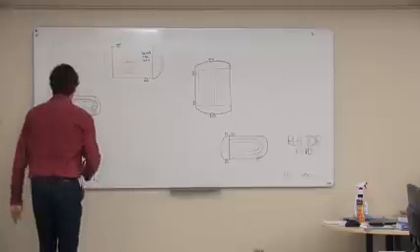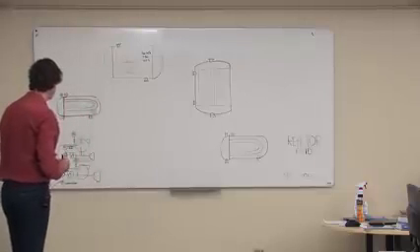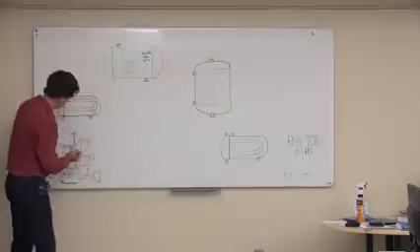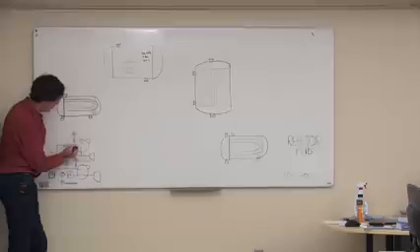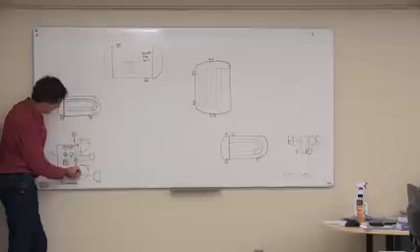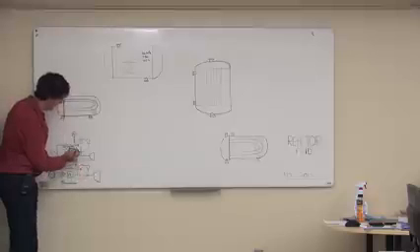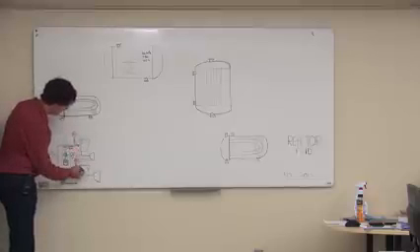So there's our pressure gauge, PI. Most of the time, the piping actually goes down a line size going into the pump. So you can show a reducer. Now, it's confusing that that looks like a turbine. It's not a turbine, it's a piping reducer. Like that. So that's going into the pump.